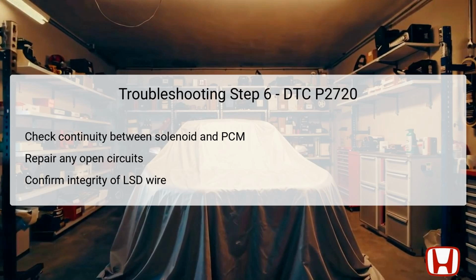If continuity is found, it confirms that the LSD wire is functional and not contributing to the DTC. However, if no continuity is detected, this suggests an open circuit exists in the LSD wire, which will need to be repaired to restore proper operation of the solenoid and prevent future DTCs.